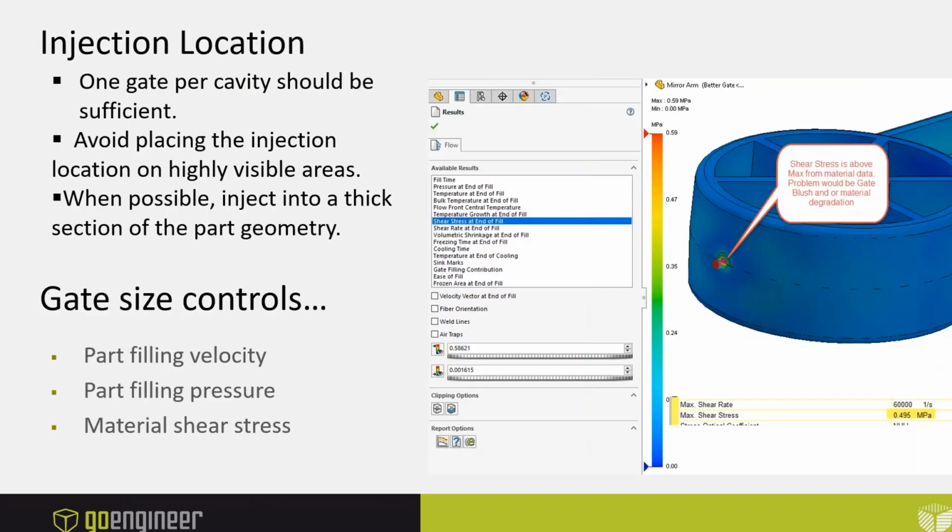And it's all done with plastics, right? So now we're just going to talk about what plastics looks like and the things you can do with it. That's my pitch, my spiel on all the different ways that you can think about SOLIDWORKS Plastics. And selecting a gate location: generally speaking, you want to gate from thick to thin, and if there's a rib behind it, that makes it better. It allows your plastic to move and flow easier.